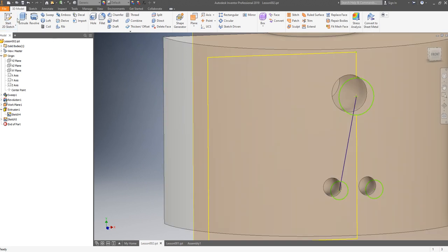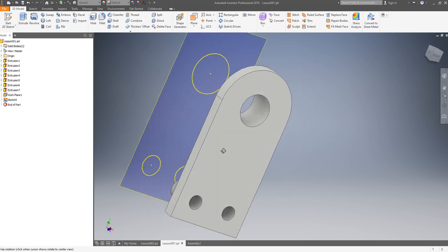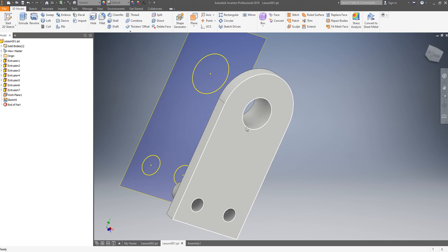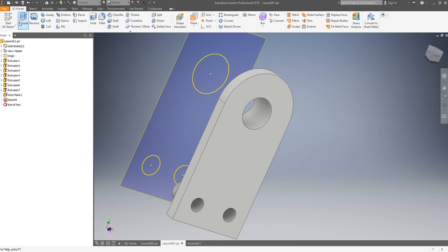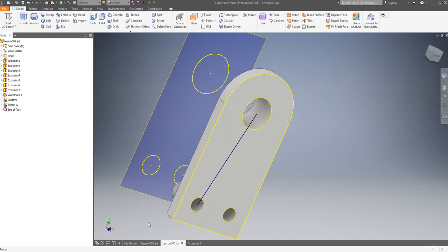Then go back there. Should be able to do a straight line like this way. So select this plane. Let's do a straight line. Sketch reference line from that point to that point. Click OK. And let's just hide some reference plane. I want to hide here.